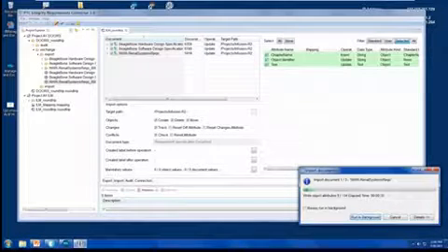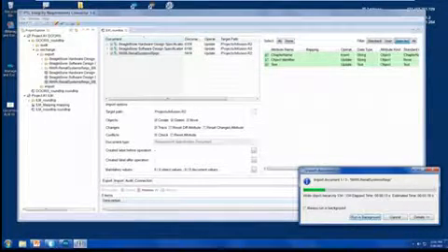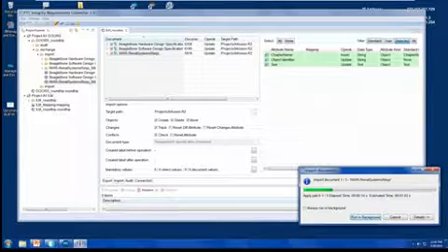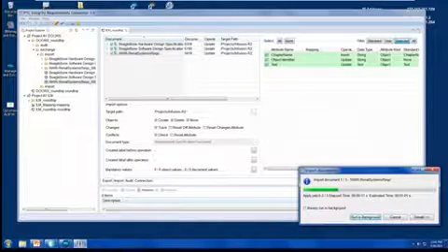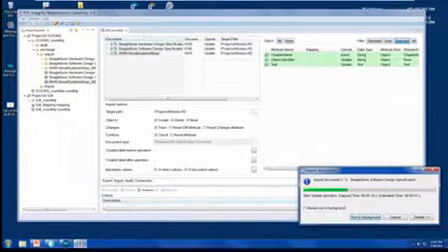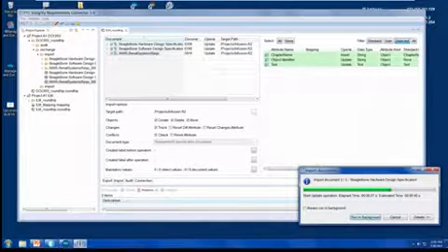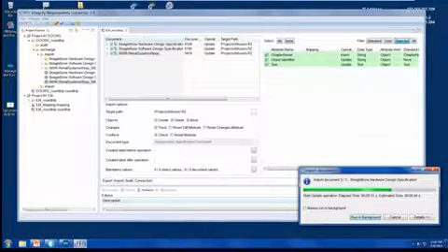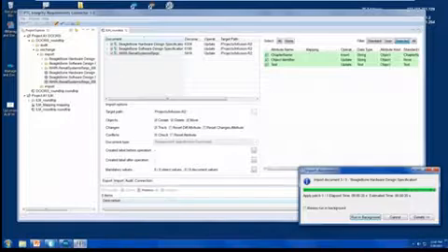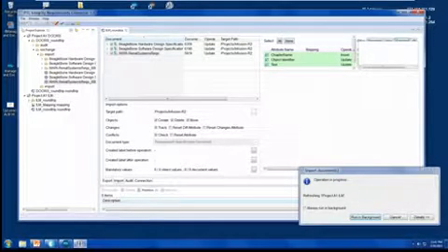And I'll just describe to you kind of what's going on behind the scenes. So IRC is querying into Integrity, into the requirements management tool. It's looking at the documents specifically in the ReqIF files, and it's traversing through each requirement item by item to see if there are any changes to it. If so, what are those changes? Does my user have permission to make an update to that item? Or is there a new traceability link that has been created or deleted since then?